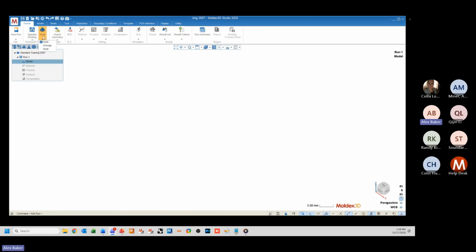To the right of that is our meshing style. We have 3 different meshing styles in Moldex3D. Solid is what we'll be using 99.95% of the time. It's pretty much the standard meshing style for Moldex3D at the moment. And this is what we call the boundary layer mesh type of meshing method. Below that is eDesign. This is the voxel type of meshing method. This will be used if we can't create a mesh in solid.